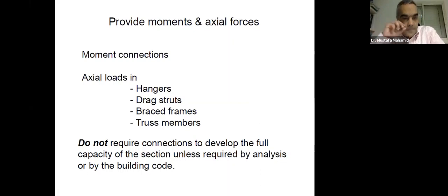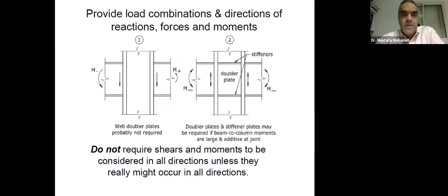Axial loads in hangers, drag struts, braced frames, truss members, show the axial loads there and do not require the connection to develop the full capacity of the section. That may lead to way over designed connections.